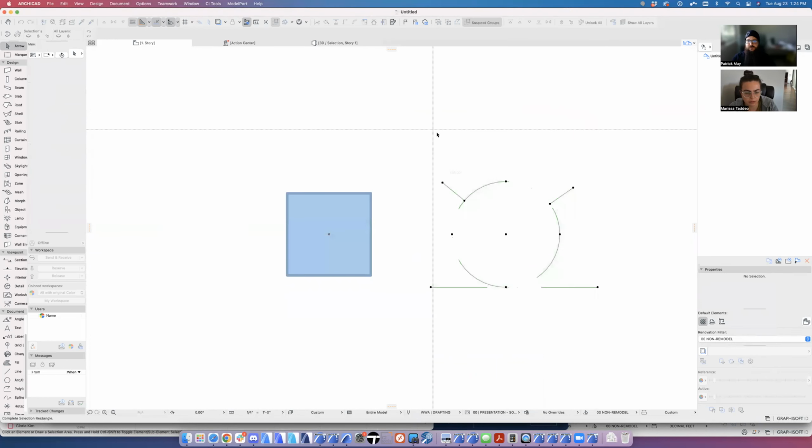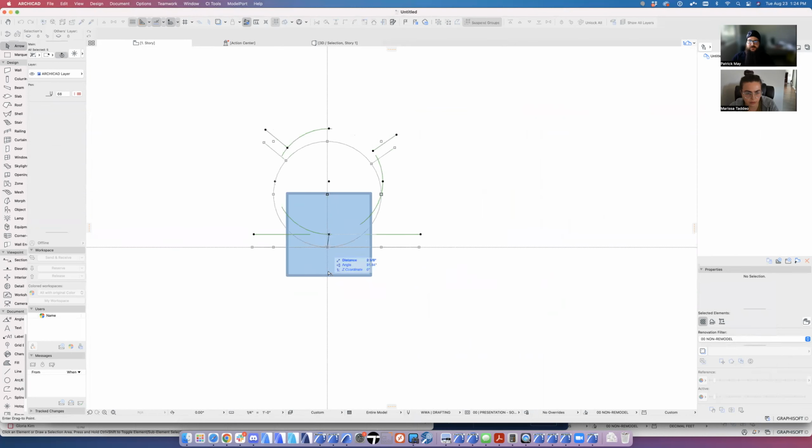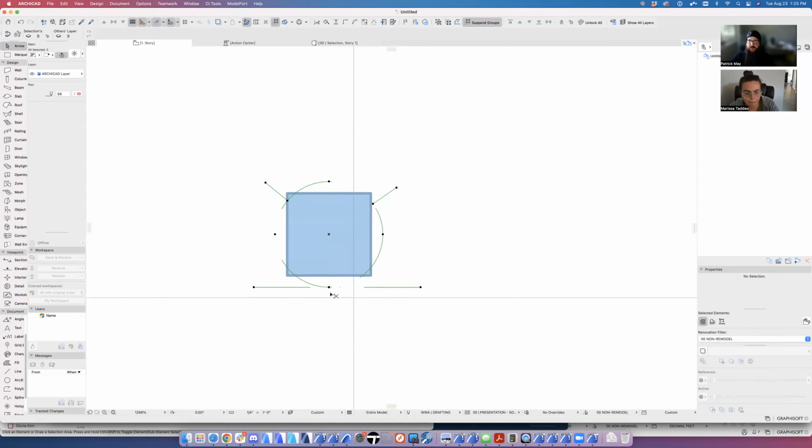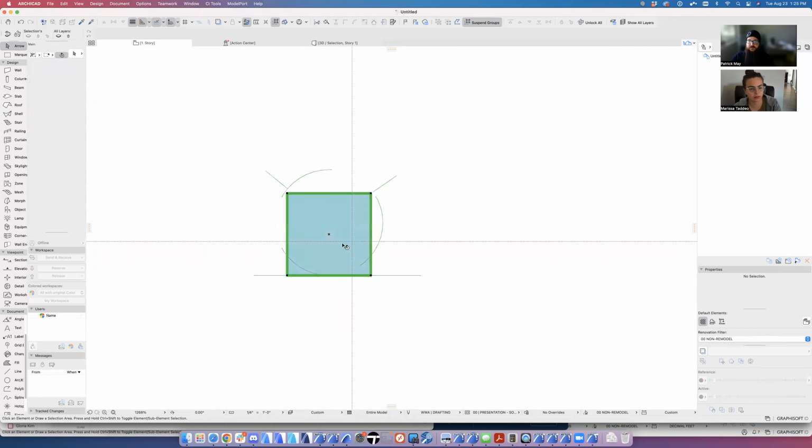And now I need to place my 2D symbol with where it's going to align with this 3D. So if, for example, I want this back edge here to be up against the wall because it's a sconce, then I would place this right here. If it were a ceiling fixture and I want it to be centered on that fixture, I would place it right here. That makes sense. Because they're not the same size, I need them to align where they need to be justified relative to this 0, 0 position. So for a wall sconce, I would want the wall edge of the 3D portion and of the 2D portion to align. So I'm done with the 3D portion.